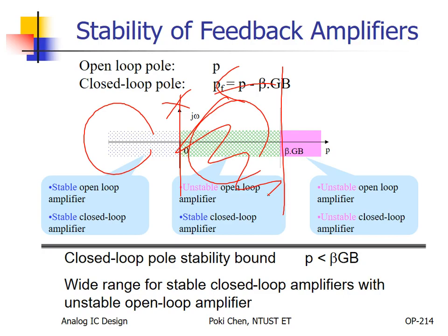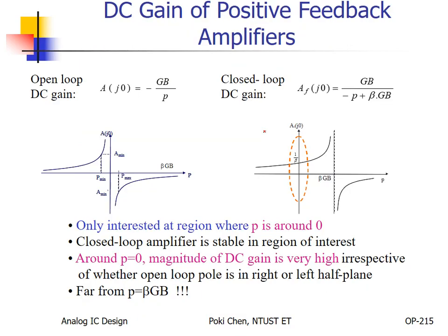Yeah, so in the past, we applied negative feedback two times. First of all, for op-amp design, and then for your negative feedback application. It doesn't make any sense, right? So here, usually we hope you can design with positive feedback for the op-amp to enhance the gain, and then apply negative feedback to make the overall application stable. That is the logical thinking. And this never happened in the past.